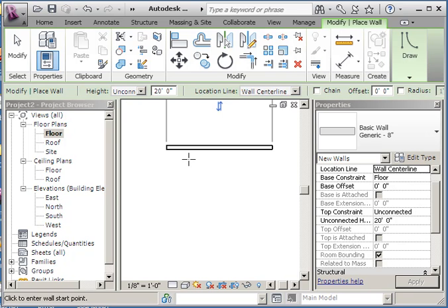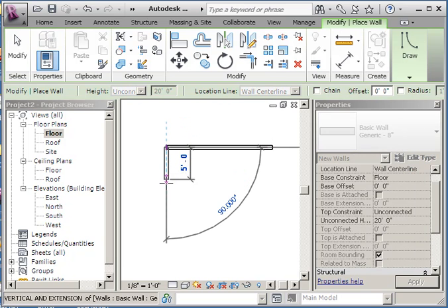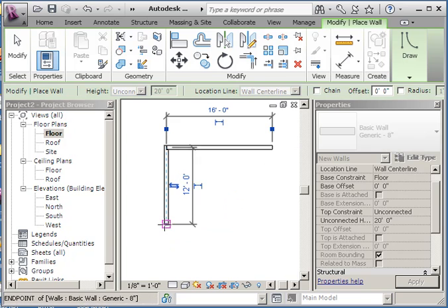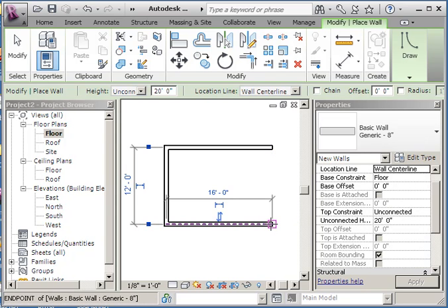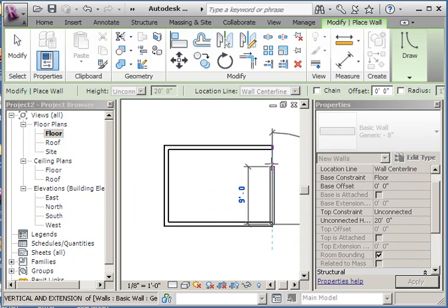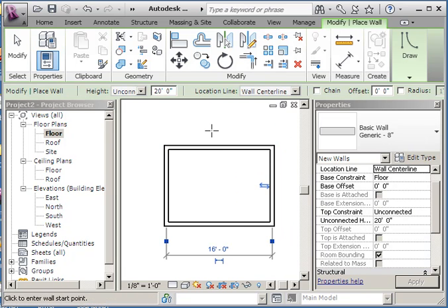And so that's how you can make one wall at a time, and then you would click on the corner and you would drag down to make the second wall. Click that corner, drag over to make the third wall. This program does a good job of inferring for you. See the little blue dotted lines, angles and things that are kind of helping you out.